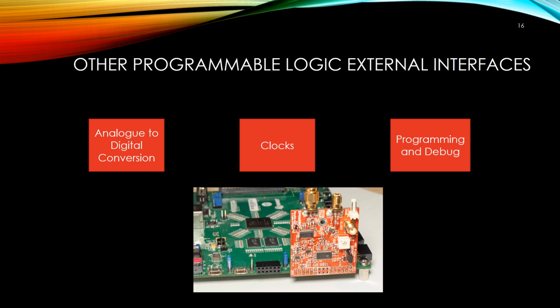Programming and debug. A set of JTAG ports are provided in the PL section to facilitate configuration and debugging of the PL. Although more secure methods are normally preferred in deployment, JTAG configuration is often used during the development phase. This facilitates, over JTAG, support for debugging with both ARM and Xilinx tools.